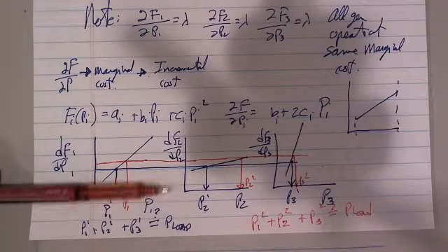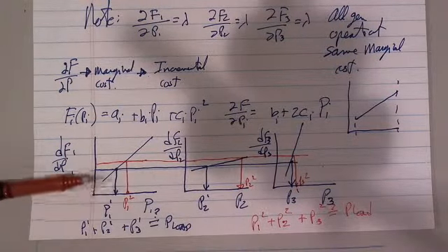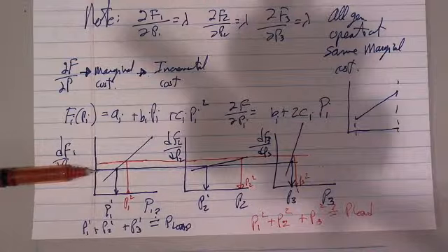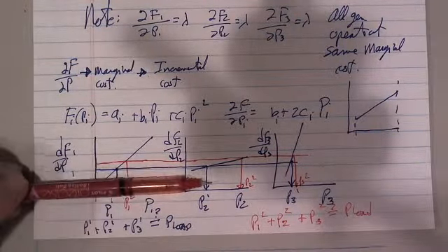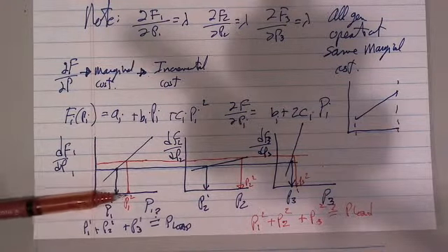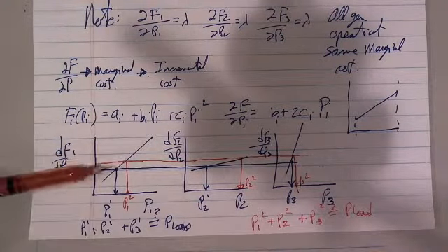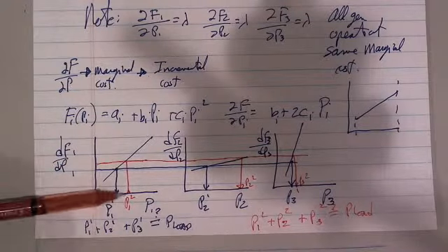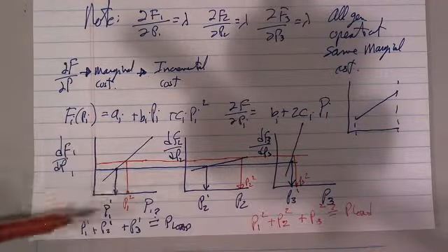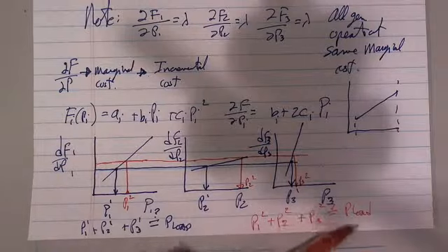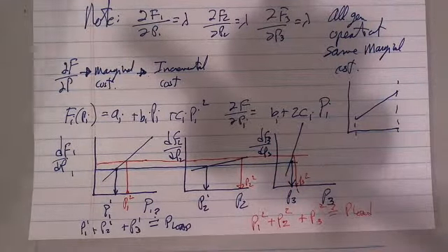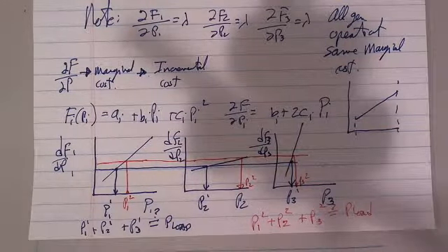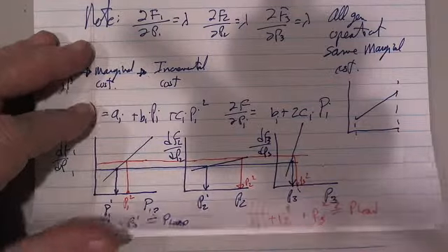So all I need to do to calculate the exact economic dispatch with these linear functions is to move this line up and down. Every time I move it, I calculate the intersection and add them up and test that. Is it within the P load value that I want? And you can say, well, okay, if it's within 0.01 or 0.001, you're good enough, and then you can stop.